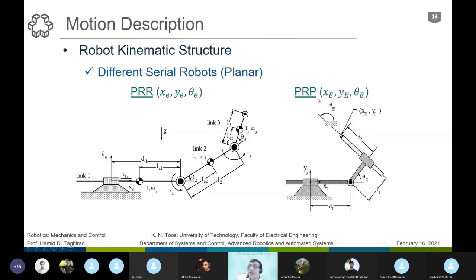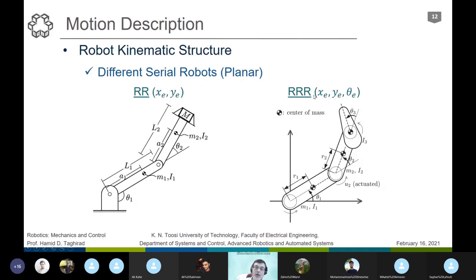So if we add another joint here, for example, another motor here, or in the previous one, instead of 3R, we add another to make 4R, if we put another actuation, it doesn't provide us with extra degrees of motion. We cannot have x, y, theta, and another theta or phi, because in a plane there are only 3 degrees of freedom. But we are redundant in terms of actuation. We have more freedom in how to move, and we will talk about that in redundant manipulators.